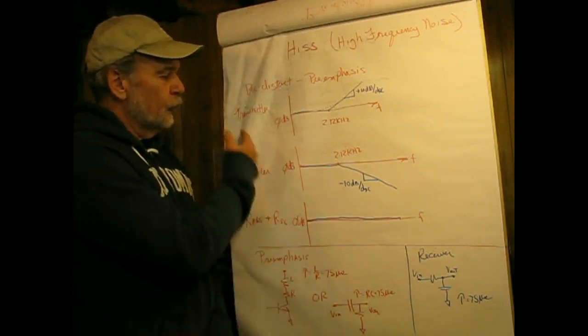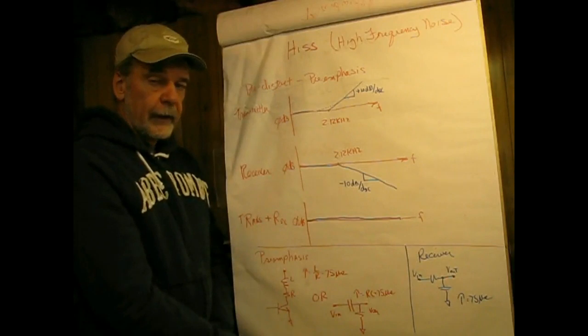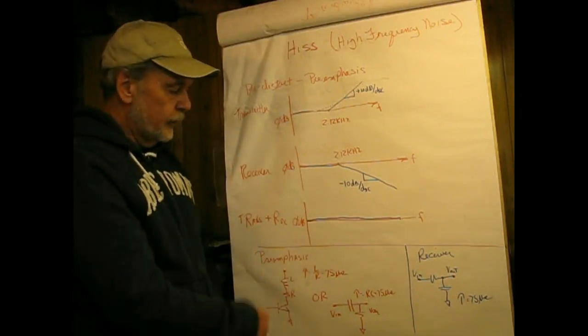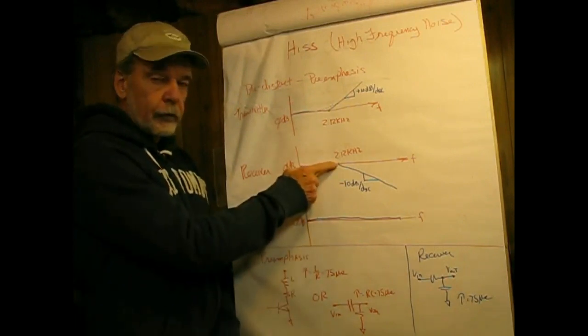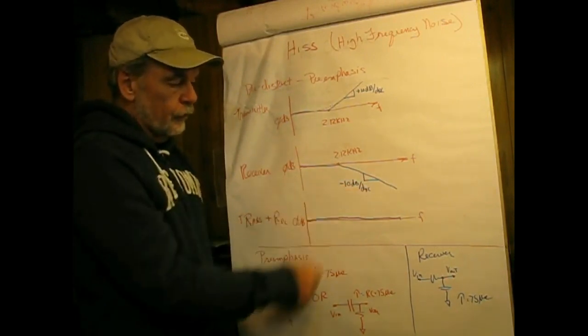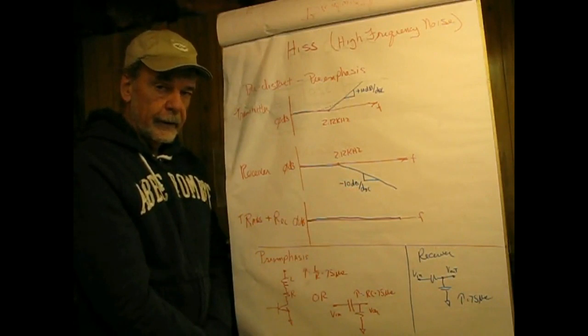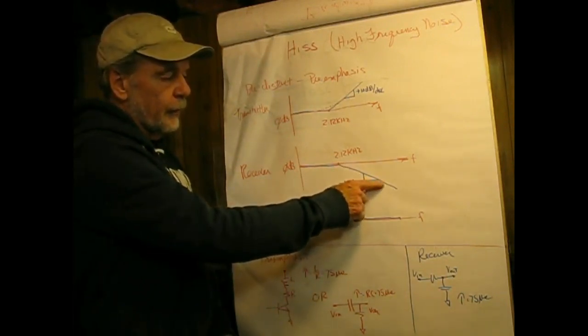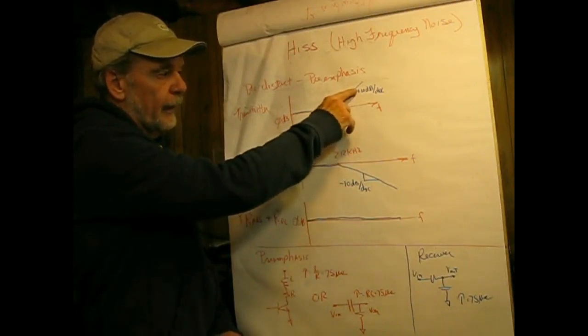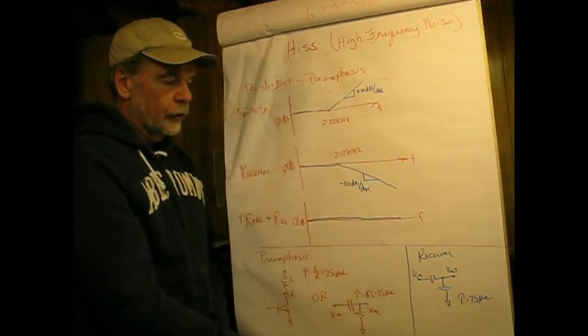Now, to make up for this pre-distortion, every FM radio made has a de-emphasis network. That's this guy. It has the same turnover frequency, only its response is negative 10 dB per decade. So as this reduces the hiss, it'll also take our emphasis and put it exactly where it should be.